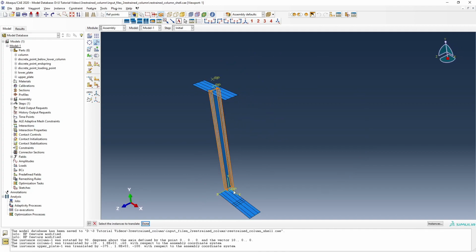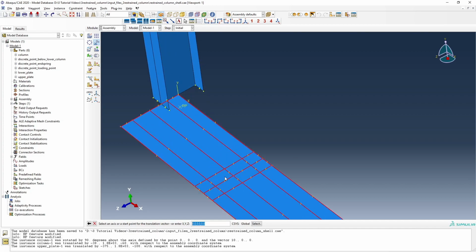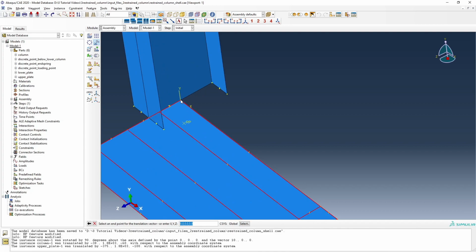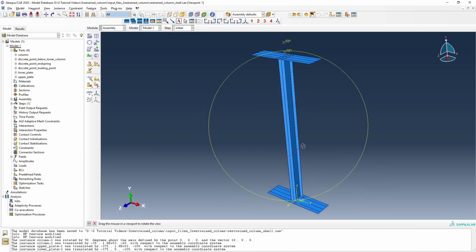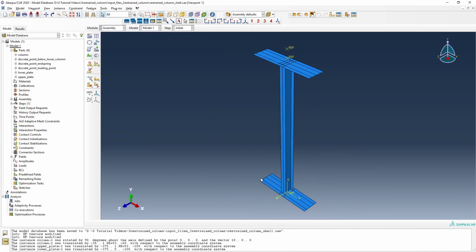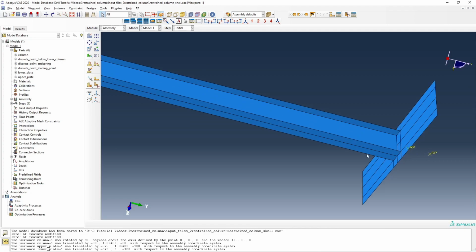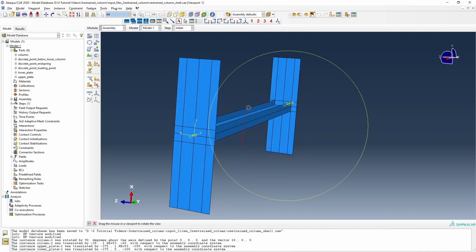And now we also need to move this instance, and then a similar process. So we have this point 0 0, and then we go to this 0 0, then accept the position of instance with OK. And now let's cancel the procedure and then go to auto fit and have this orientation. So now we can rotate and see if everything is okay. So yes, it is now exactly the way how we like to have the connection.